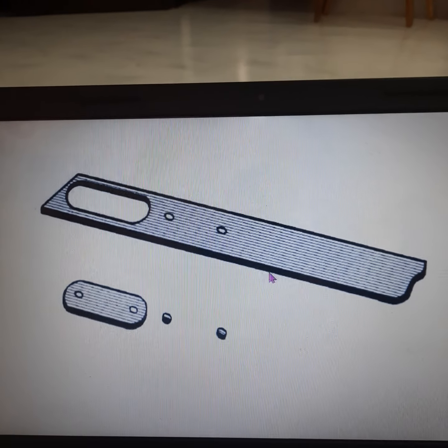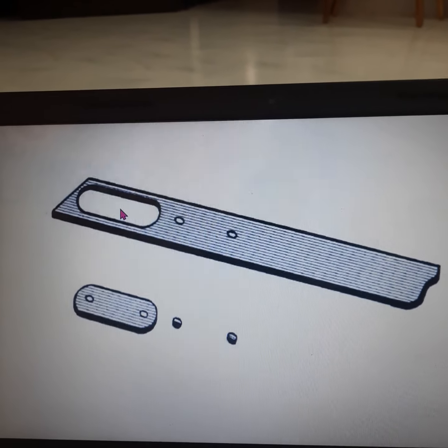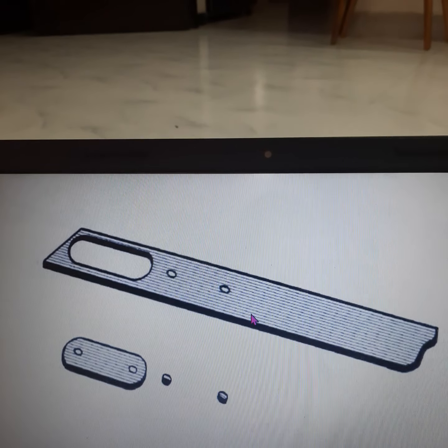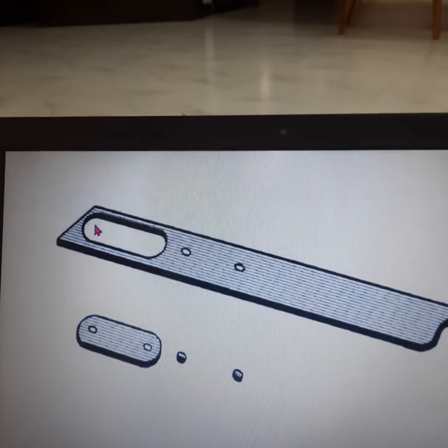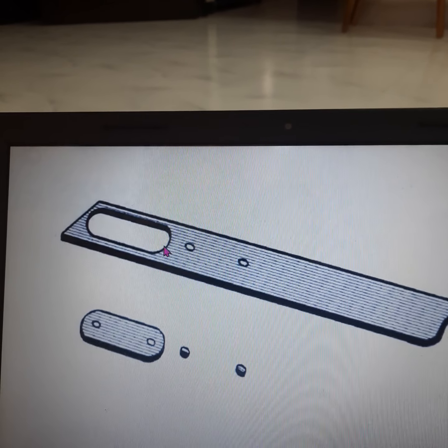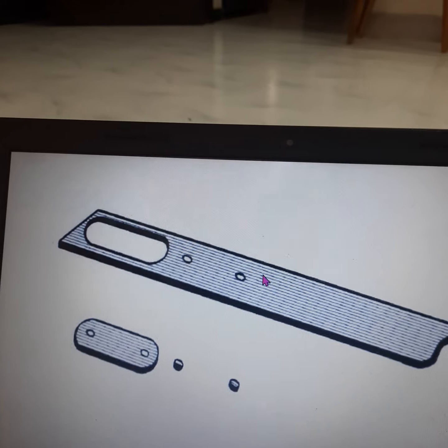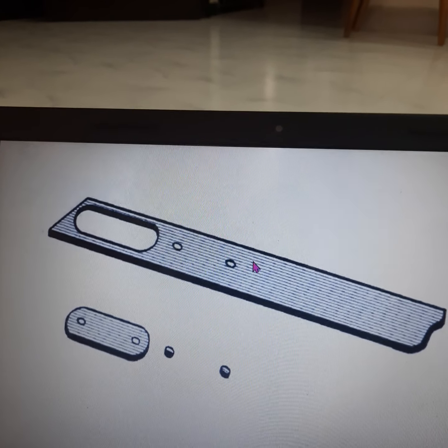The feed strip, after cutting out the first sheet metal product, will look like this. The first product has been cut out from the feed strip, and this is the condition of the feed strip at the end of the second stroke of the press.